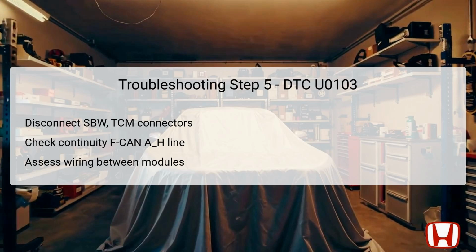If continuity is present, it signifies that the wired connection for FCAN-AH is functioning correctly. Should it fail the test, it indicates that an open wire exists between the SBW shifter control module and the TCM, necessitating further investigation and repair.